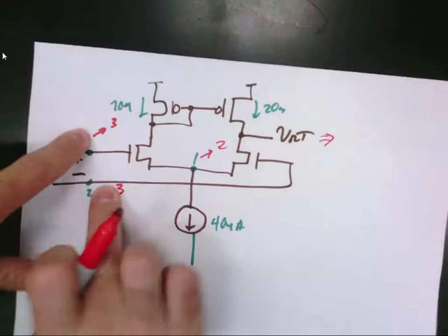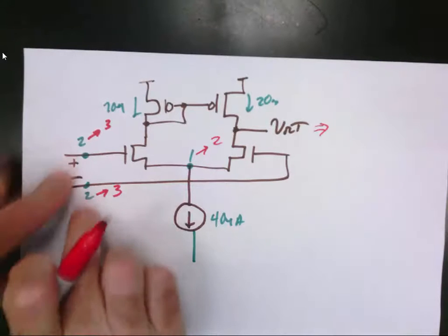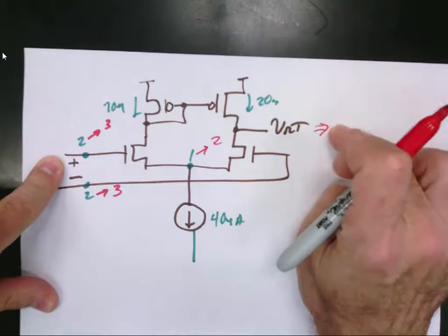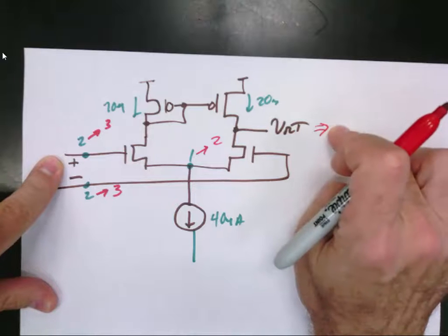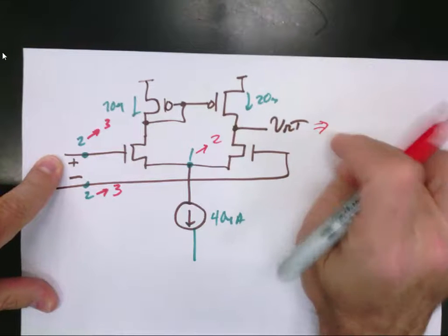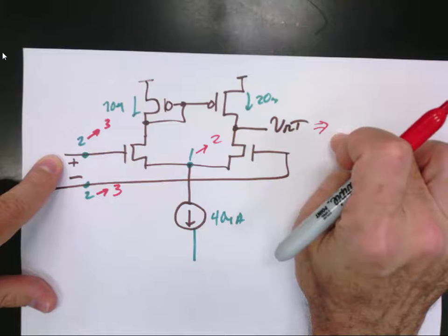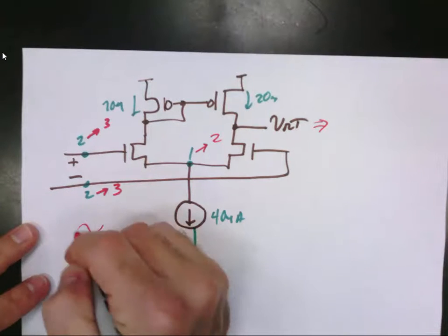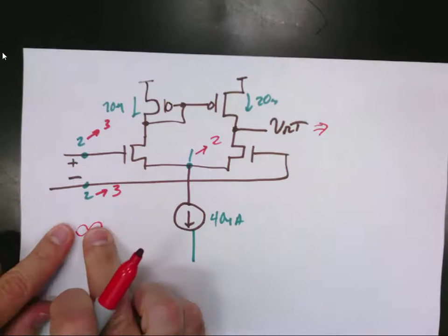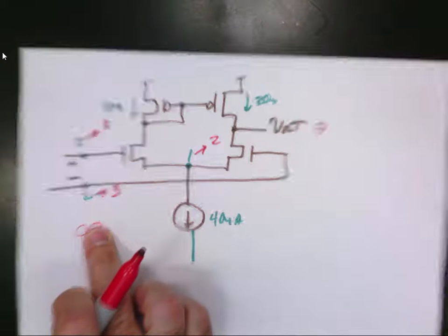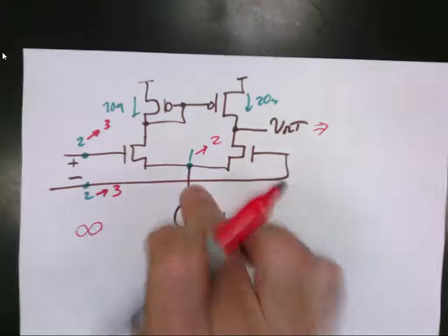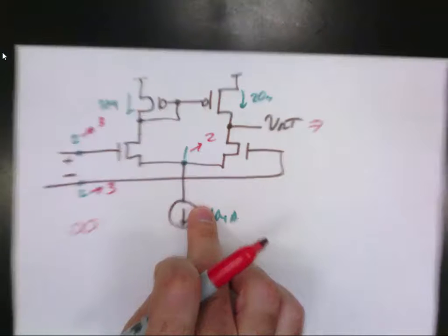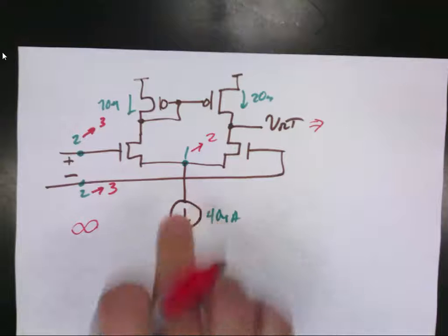So even though I got that noise bouncing back under that common mode signal that I don't want, it's not appearing in the output of my diff amp. So I'm not going to amplify that, and I'm not going to hear it. And this is why they use fully differential signals. Also, they can reduce the signal level because they don't have to worry about noise, so your signal-to-noise ratio stays high. Very, very common circuit. You probably have thousands in your phone right now. Any questions?